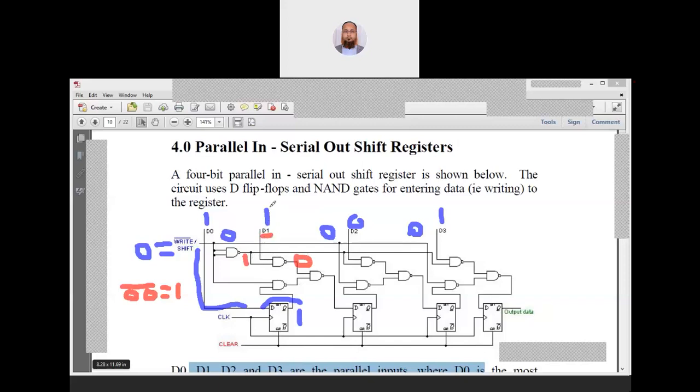The performance of this does not depend on this data. So this will be decided by further operation. Then what is the output here for this flip-flop? When the clock comes, normally the delay of the flip-flop is much greater than the delays of these gates. Like, maybe the flip-flop may have a delay of 50 and these gates may have 10 each. So the delays of these gates are smaller.